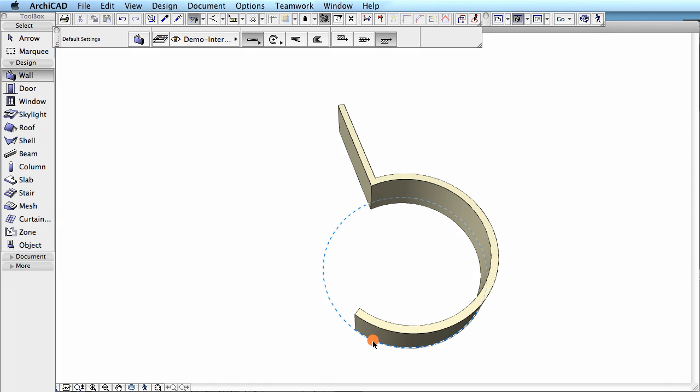By clicking on this dot, we can activate the guideline. This is important because by doing so, designers are able to keep only the needed guidelines, even in cases of complex design situations or multiple elements. Now let's find the main Y direction by moving the mouse over the previously created straight wall segment. The temporary guideline appears with the orange dot. This dot can also be used to reposition the temporary guideline in the 3D window.